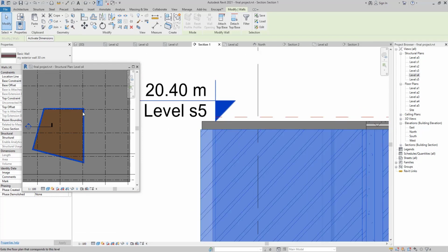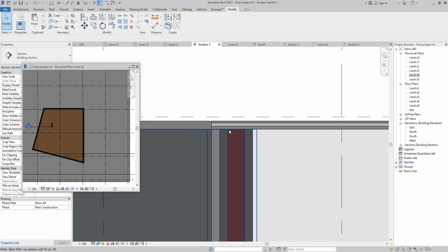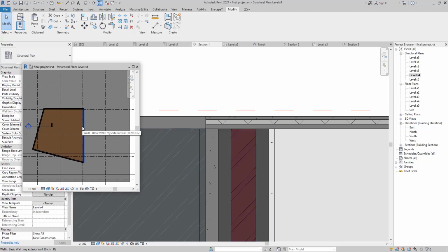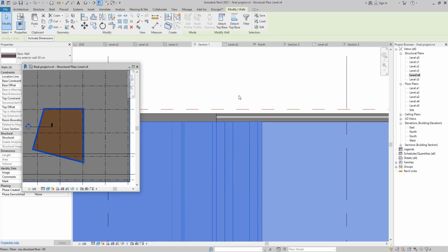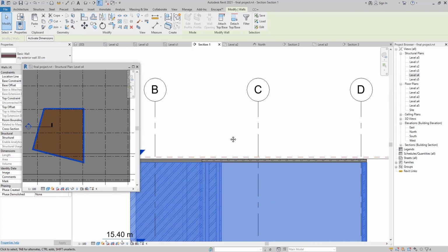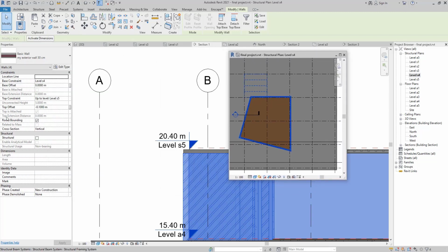And after that, since we choose our wall, we are going to attach top to our floor. Then it looks fine, and we can see it here, everything looks fine. But we want our wall to come up, for example, 90 centimeter to create, for example, a small rooftop or balcony, something like that, for example to stop the rain. For creating that, we just going to click our wall. After that, we are going to here to choose the top offset for 90 centimeter. Here we go.